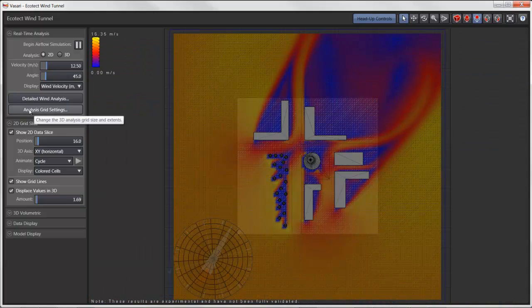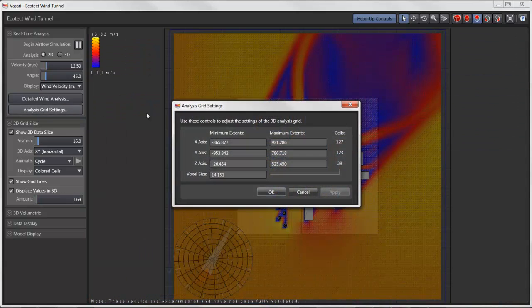So you can change that by going to analysis grid settings. Typical I use something like between 5 and 8, and that gives also more accurate results for the simulation, but it takes a little bit more time to simulate. So I will try it with 7 in this case, and typically it also creates maybe a little too high volume around the building. So I also pull that down, in this case 150, I think it should be okay, to have not too many analysis cells.